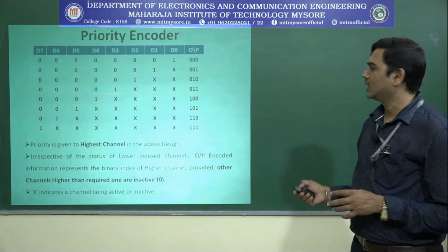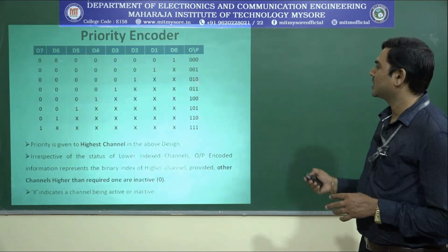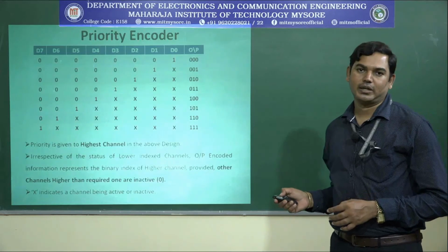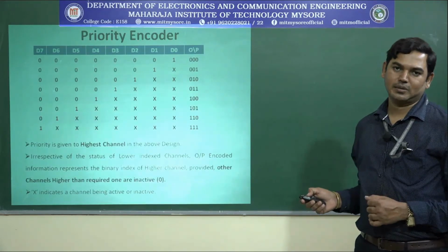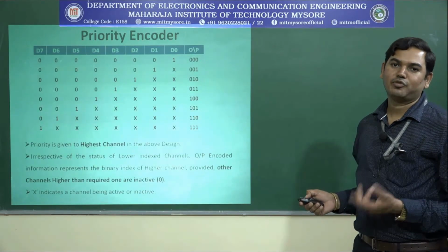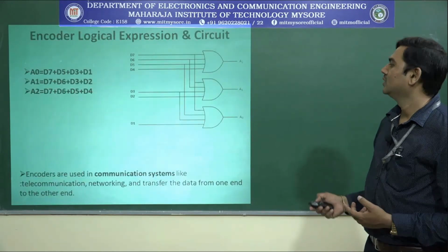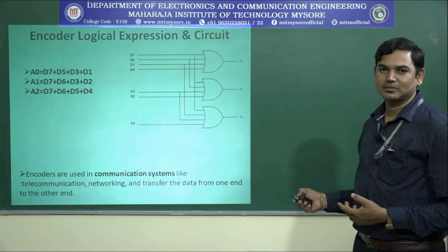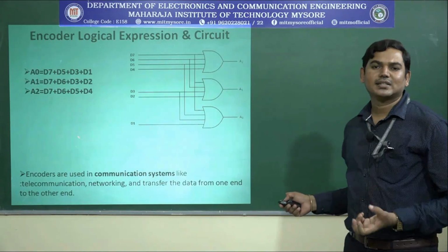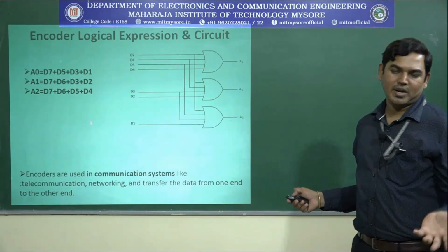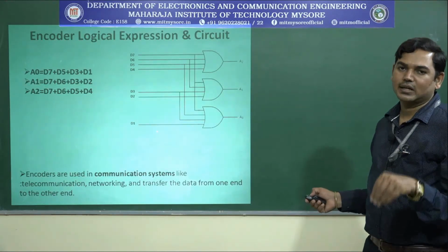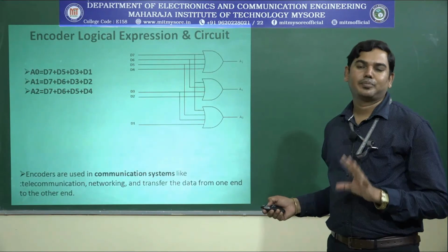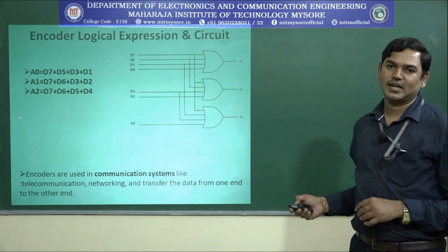In such a situation, I can simply transform this table into an HDL statement, which is known as the behavioral description, and still it is possible to obtain this kind of equation and logic connection, synthesize the netlist, supply that to a tool and get an 8:3 priority encoder synthesized.